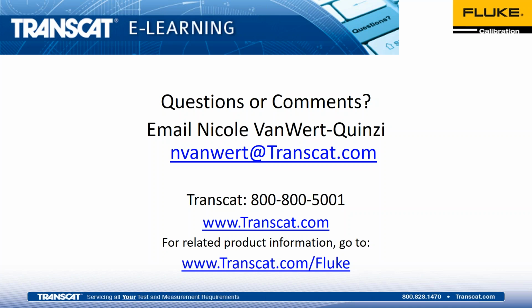On my side of the Fluke fence, I'm part of the Fluke Calibration group, so the 724 is not in my product offering, but you can get custom cabling done. With most RTDs, you're working in resistance, so you don't have to worry about shorting something or blowing something up because you're not applying a voltage or millivoltage.